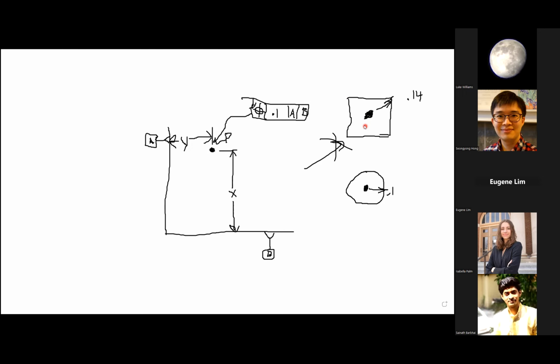We would rather have this hole move less than or equal to 0.1 away from the center. That way we know, as long as it's within that circle, then we know that hole is going to line up with, let's say, a bolt that we're trying to put through it. So this is a much more specific way to control that.